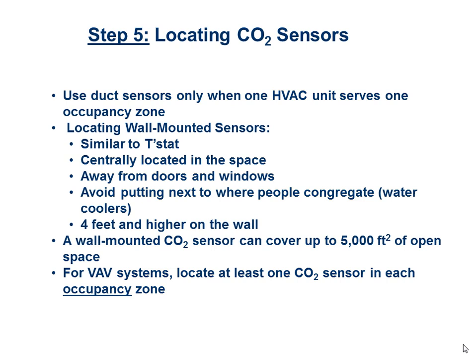So for single zone systems, the only time you put it in the return duct is if it's one giant room with no dividing walls or anything like that. So if you've got a conference space at a hotel and it has those 3 dividing walls, don't put one in the return duct. So just only if it's one big space.